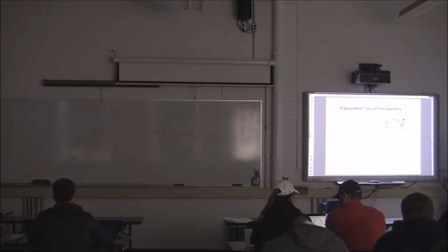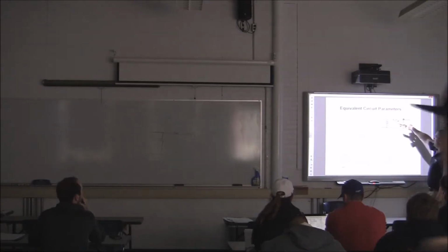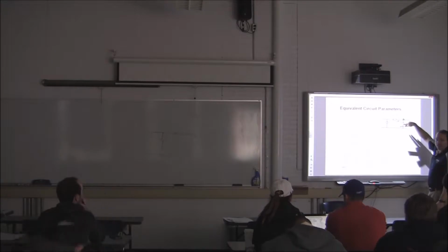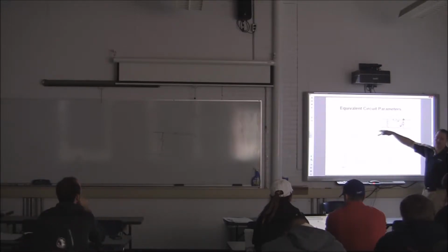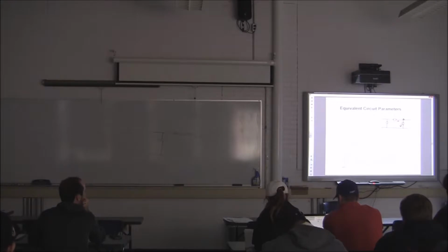Okay? I can do the same thing at this one, right? So I know what the voltage is at this terminal. I know the impedance of this element here. And I'm assuming this is my reference. So it's VR minus 0 divided by, or is it not divided by? What is Y?